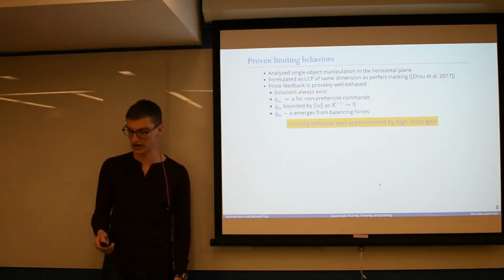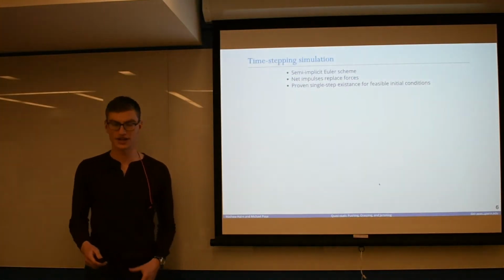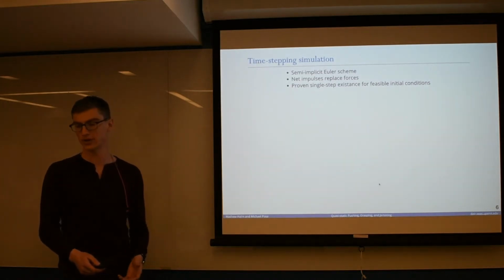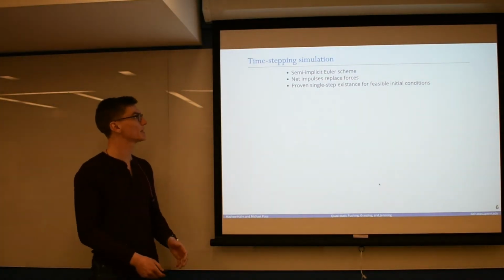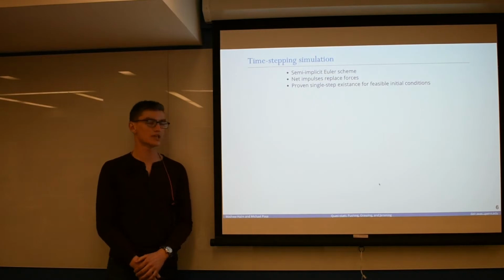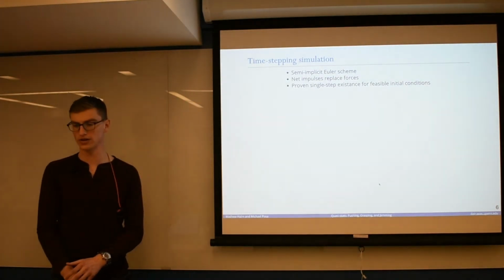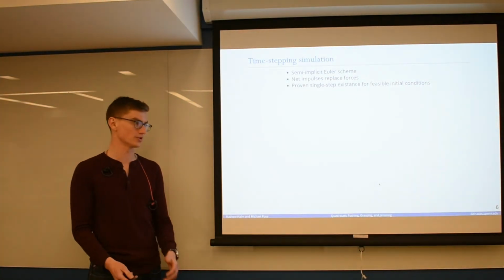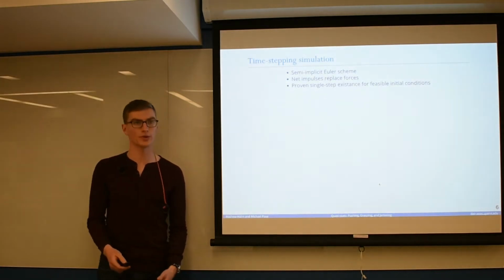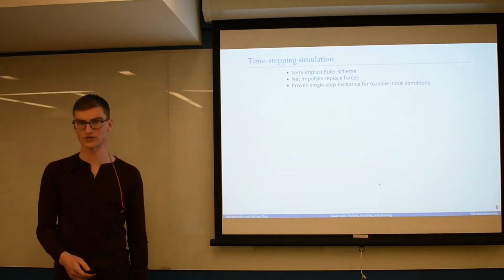To that end, we created a simulation scheme from our model that is a time-stepping scheme. It uses a semi-implicit Euler method, which replaces forces with net impulses over a time step. And again, we were able to prove existence of solutions over a single time step.